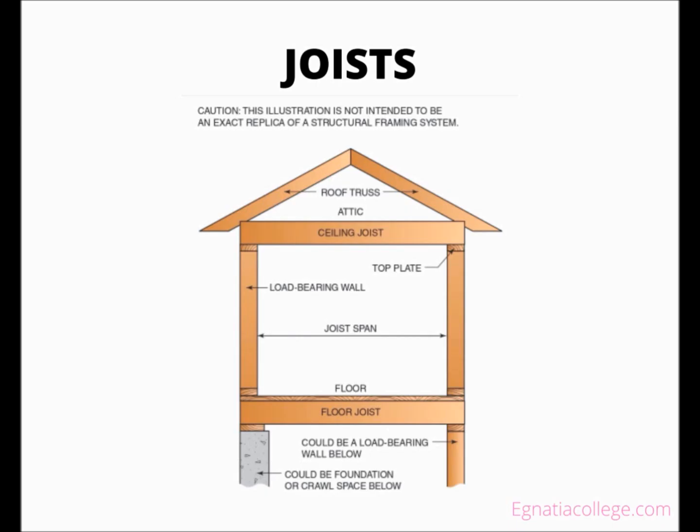regulations. Some codes do not allow any holes to be drilled in the middle 1/3 of a span. Other codes require a joist to be reinforced with exterior grade plywood if a large diameter hole is to be drilled through it. Some codes do not allow a hole to be drilled in a floor joist in the area that has a load-bearing wall directly above it. Thorough code knowledge is required before drilling and notching joists.